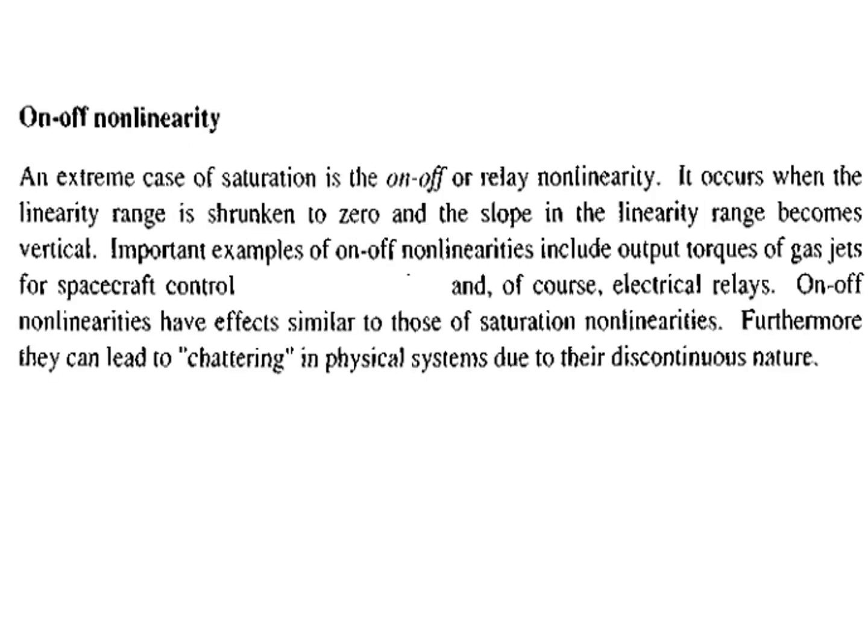Another nonlinearity is the on-off nonlinearity. It occurs when the linearity range is shrunken to zero and the slope in the linearity range becomes vertical. If you see that the dead zone is shrunken, there is no slope, and it is vertical. In gas jets for spacecraft control and in electrical relays, this on-off nonlinearity will lead to chattering and is discontinuous in nature.